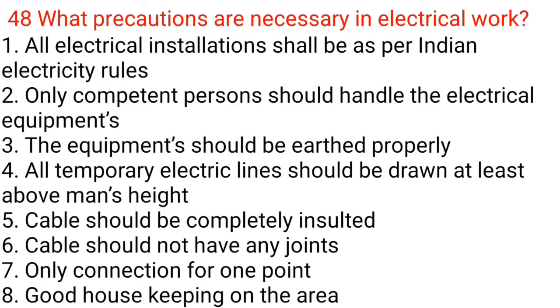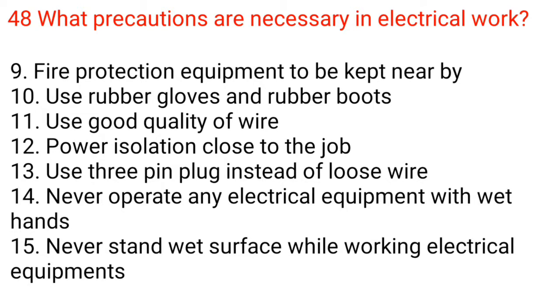7. Only one connection for one point. 8. Good housekeeping in the area. 9. Fire protection equipment to be kept nearby. 10. Use rubber gloves and rubber boots. 11. Use good quality wire. 12. Power isolation close to the job. 13. Use a 3-pin plug instead of loose wire.